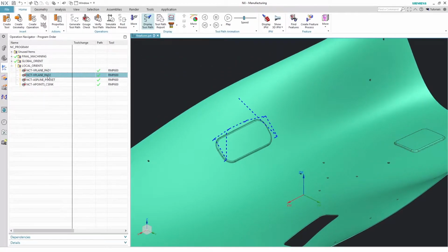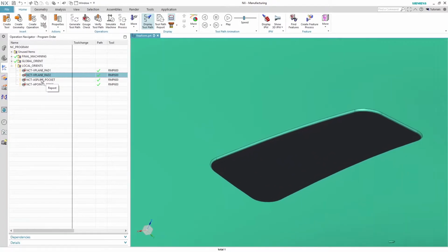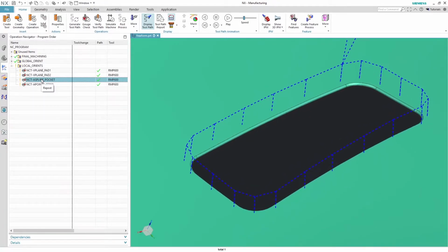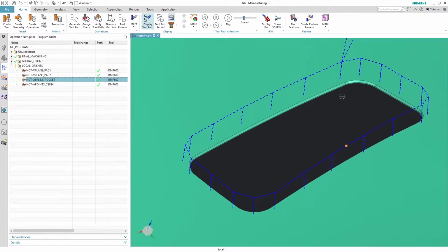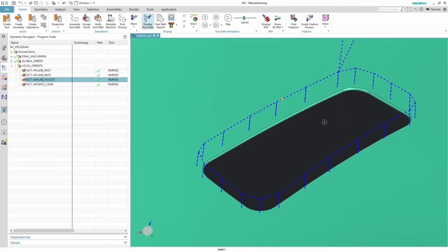We do the same thing for pad 2, and then we're going to use something called an adaptive spline for the cutout. And in that, all we need to do is probe about 1 to 2 inches around the periphery of the cutout, turn that on, and allow NCT to adapt that cut path to the contour of the part.